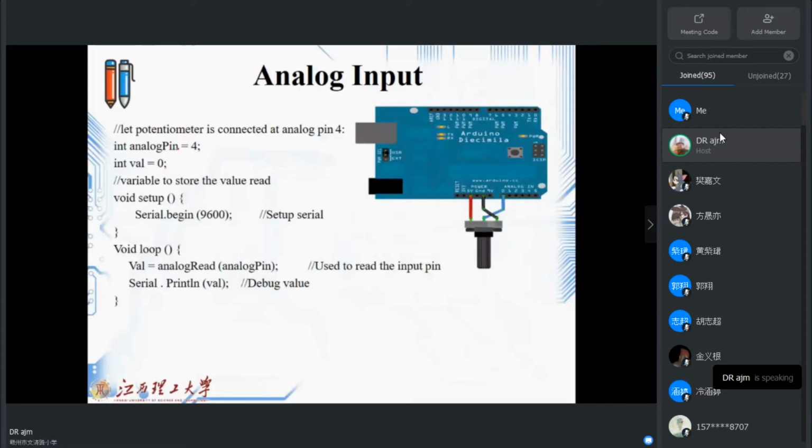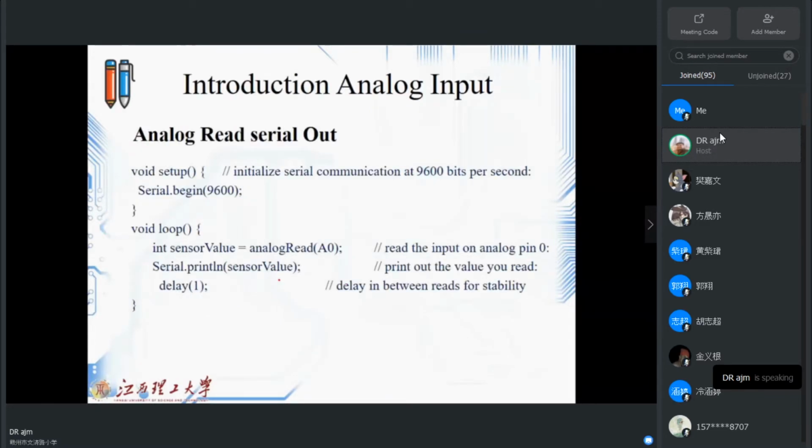Okay, something that I used here is wrong. This value should be 0, because I connect to pin number 0. Then it's very simple, because I want to show it on the serial monitor. First, I do the initialization for the serial monitor. Then in the loop, I simply read the analog value and then print the value. Very simple. Whenever I move my input, something should show on the serial monitor.